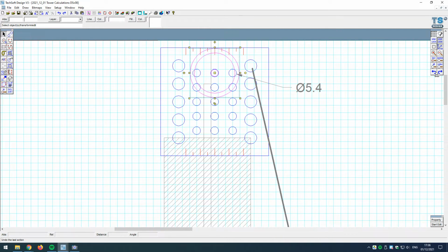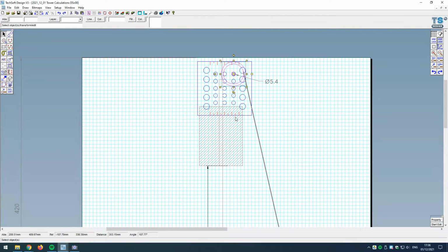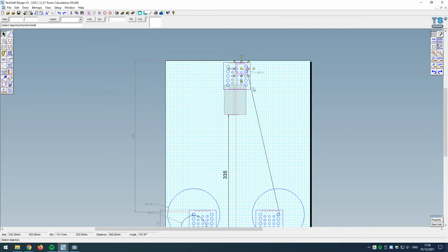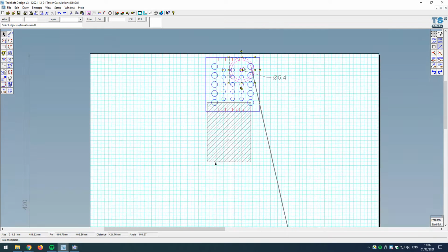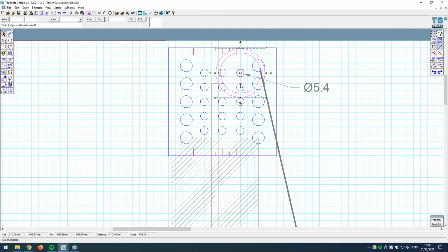My feeling here is that often, if the tower frames aren't precisely manufactured, they can be a little bit wonky at the top, and that means that we can accommodate slightly wonky tops of towers, and perhaps have the top pulley axle running into this hole, for example, on this front face bracket, and the bracket that's on the second half of the tower that might be slightly wonky, we could then be running it into another hole to make sure that the actual axle itself and the corresponding pulley are held horizontally aligned to the ground floor.